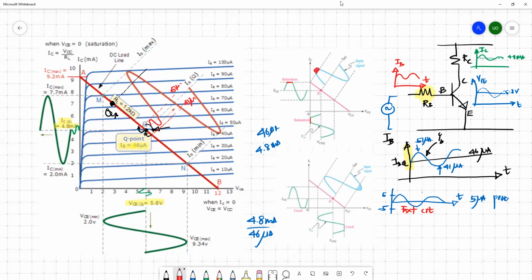Then you can't see any amplification in the collector current. It is pushed to the saturation current and maintains that value during that part of the cycle. You can't see any collector-emitter junction voltage amplification either, because it's suppressed to 0. Once you increase your base current, you can observe that your collector-emitter junction voltage simply stays at 0.